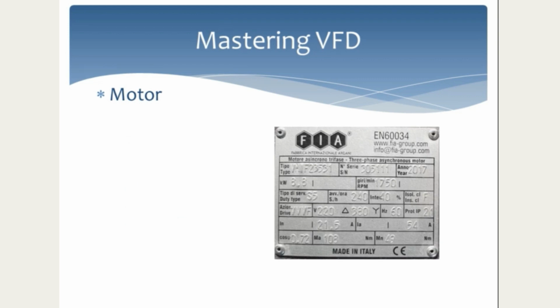Here I am sharing a motor's nameplate. It might seem complicated, but we will go through the parameters which we require. Here we will locate the required parameters. So here we have kilowatt, which is mentioned 8.8, and the speed, which is mentioned 1750, the rated voltage of the motor, rated frequency of the motor, and the rated current. And we need to know motor poles and rated slip.